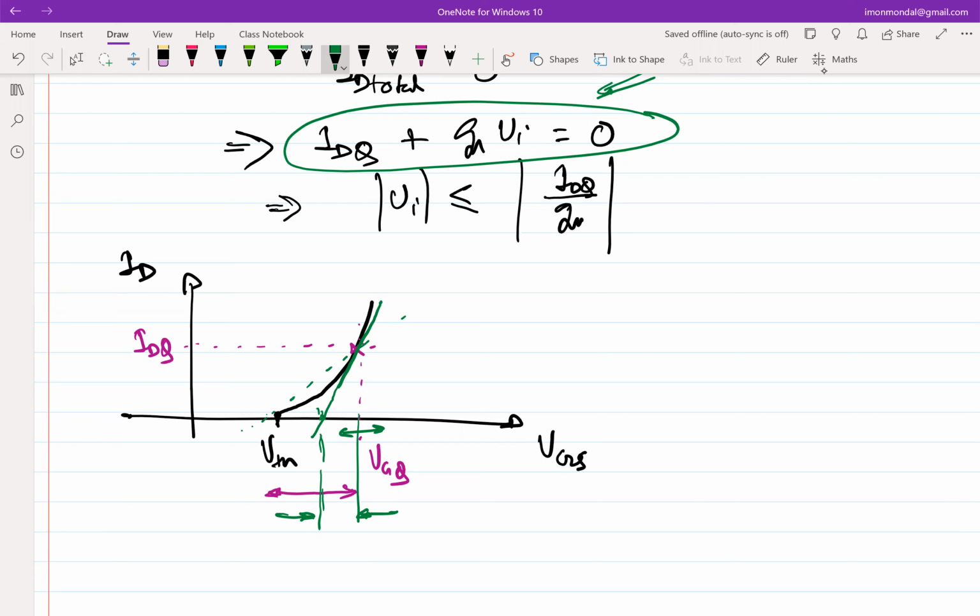That inherently is much more linear than your total current going to 0, because the allowable swing that I am limiting my device to operate in is less than what it would have experienced if I would have allowed the total absolute current to go to 0.